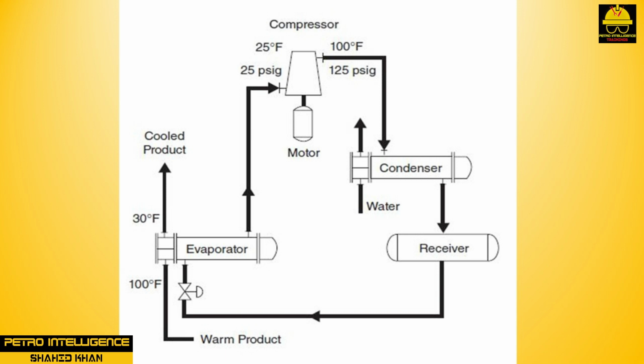In the case of an ethylene refrigeration system, owing to ethylene's volatility, propylene refrigerant rather than cooling water is used to condense the compressed ethylene vapors. No matter how complicated the refrigeration system, the ultimate ejection of heat is always directly to air or cooling water. Most large refrigeration systems operate at several levels of temperature and pressure, called stages or steps. Multiple stages are used because the application of several stages increases the efficiency of a refrigeration cycle and results in lower compressor horsepower. There are practical limits to the optimum number of stages. Generally, 3 or 4 steps are employed.